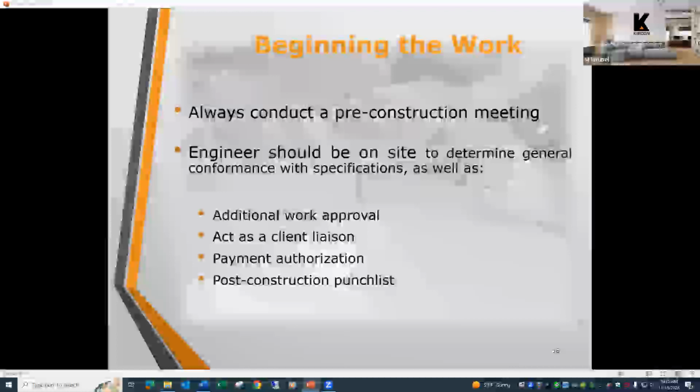And then we also review any of the contractor submitted invoices. We compare it to the original bid, and give a summary of a comparison between the invoice and the original bid, so everything is laid out so you could see how those costs are derived. And usually when you go to pay the invoice, there is a retainage in there for any sort of punch list items. And then once all those punch list items are satisfied, the retainage for the project is released.